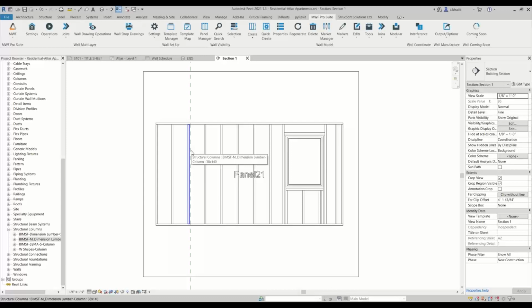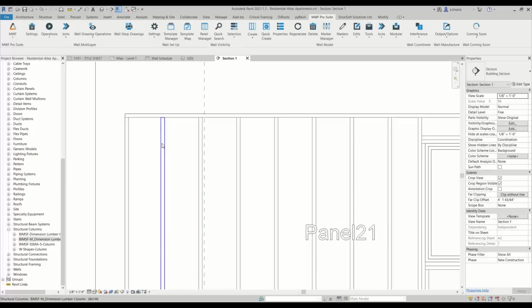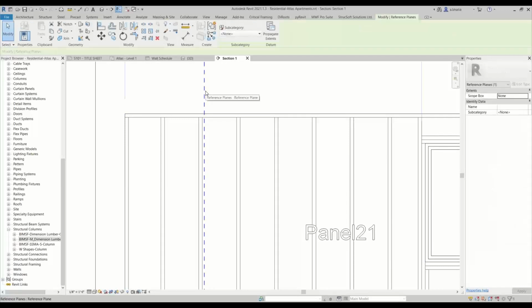And another thing I want to do, or usually when you would use this tool, is maybe you have some mechanical equipment that's being hung from the floor framing above, and it's just sitting in this little corner of the wall. You could probably place an opening to get the framing to do exactly what you want, but maybe the framing that's holding up the mechanical equipment is enough for you to support your panel, and you might just attach it to that mechanical equipment's framing. Just as an example, not necessarily it's exactly like that, but you have that option, right?